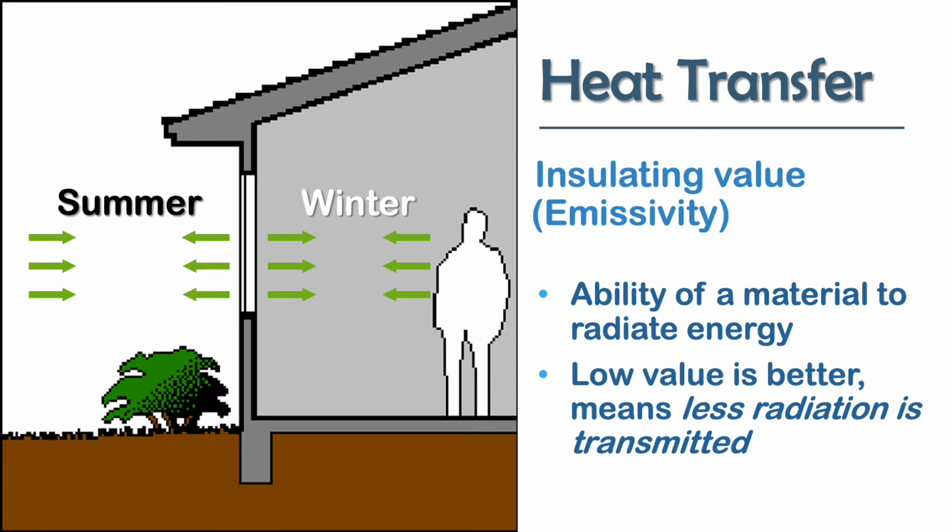Clear glass, which has an emissivity of 0.84, absorbs 84% of long-wave radiation striking the surface of the glass and reflects the remaining 16%. It's one of the reasons why we don't get sunburns when we're inside, even if we're sitting in the sun. Those of us who do get sunburned.